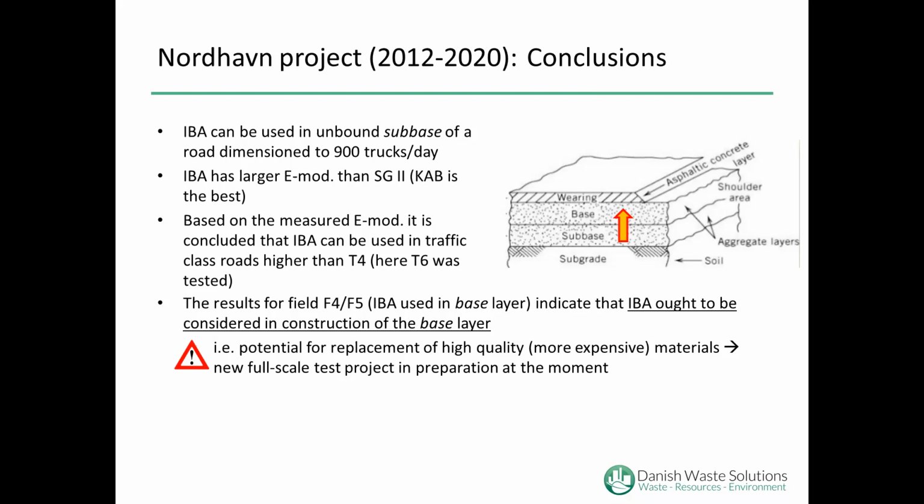Surprisingly, for some fields, the E-modulus of bottom ash was actually higher than that of stabilized gravel. It was also concluded, based on the measurements, that the bottom ash can be used in traffic roads with a stress class higher than T4, which is the normally allowed application in Denmark. Here T6 was tested, meaning even heavier trucks or heavier traffic was on the road and the road wasn't damaged.